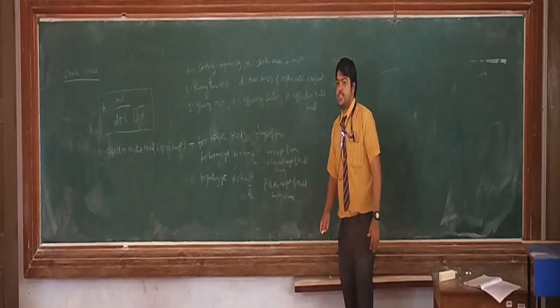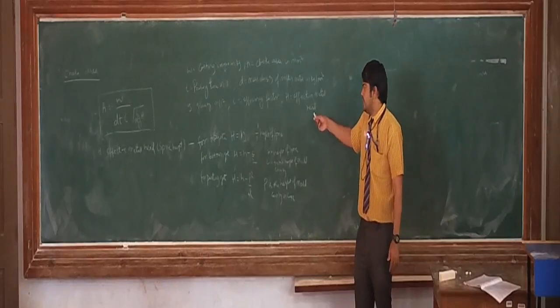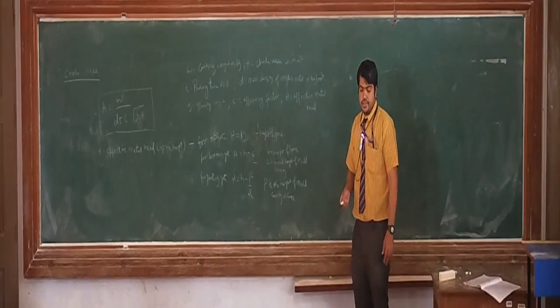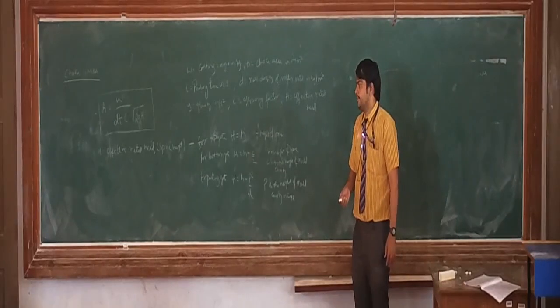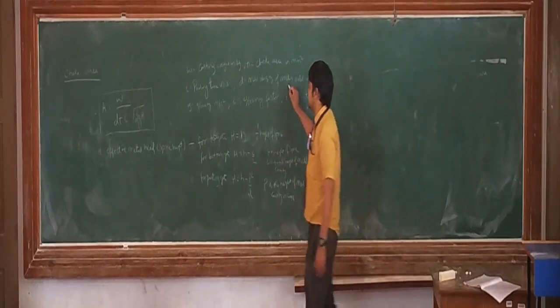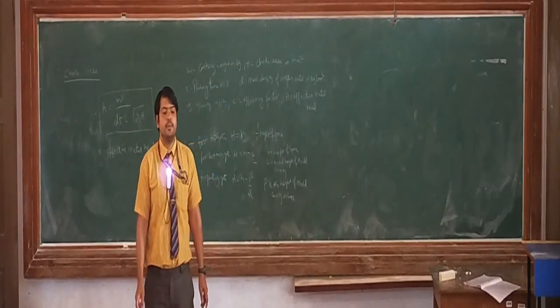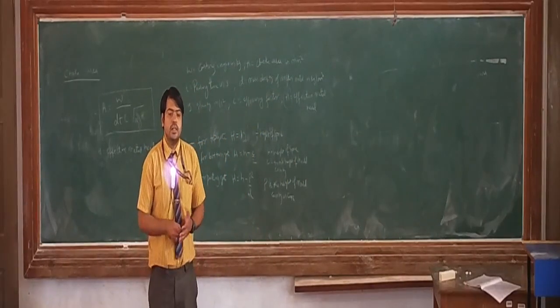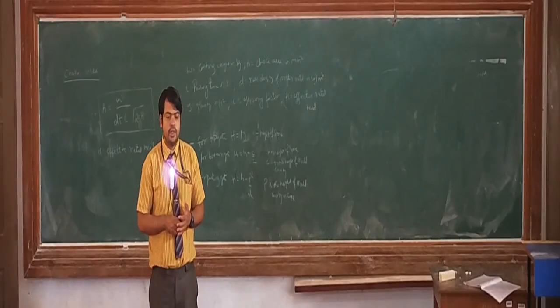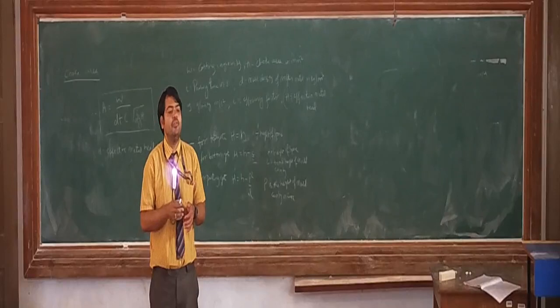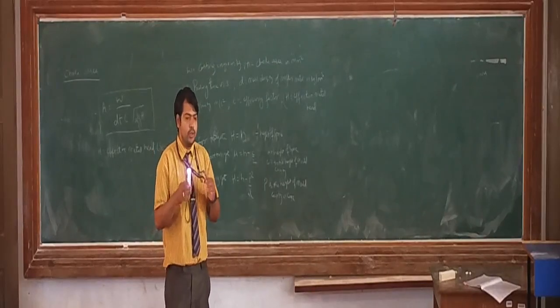C is the efficiency factor, and H is the effective metal head. Generally, that equation is derived by Bernoulli's theorem. So this effective head H is different for different types of gating system. As I explained in the last class, in top gate, directly the metal is going to be poured inside the mold cavity with the help of a vertical sprue that is going to directly attach to the top face of the casting or mold cavity.